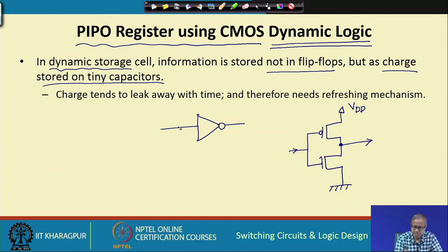Now, if you look at this point, this line is feeding the gate inputs of 2 transistors. For those of you who know how a transistor is fabricated, there is a substrate and the gate is formed on top of the substrate like this, and there is an insulating region here, and the substrate is typically connected to ground. So, you see this looks like a parallel plate capacitor.